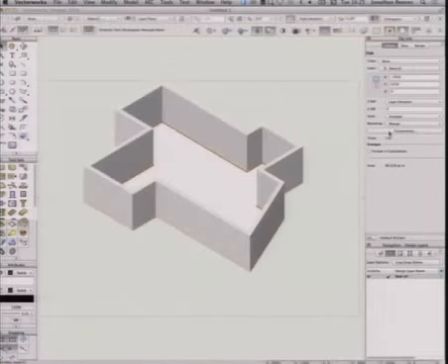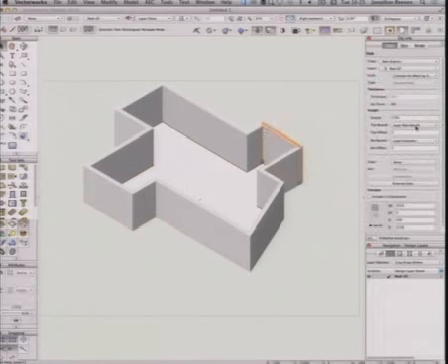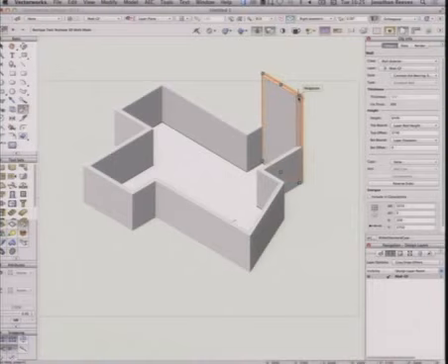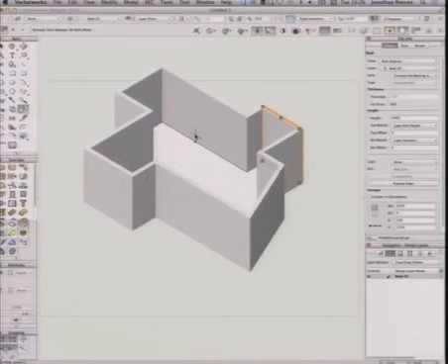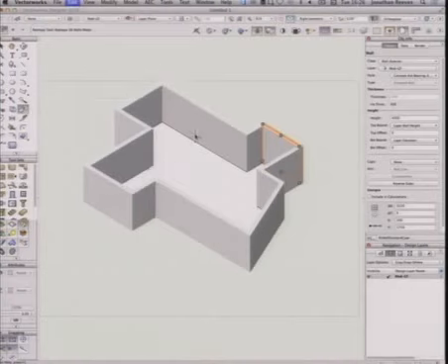So immediately those walls spring up to meet that height, and the reason for that is they were bounded to that particular layer height. If I wanted to, I could double-click on them, I could stretch them up, I could manipulate them in a completely free-form fashion, but what I really want to do is just link them to the layer height. And the beauty of that is, if my layer wall height changes, let's go 4 meters, you can see really quick, it's very easy to decide.